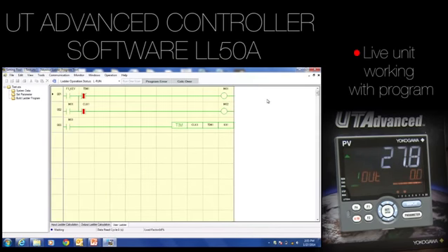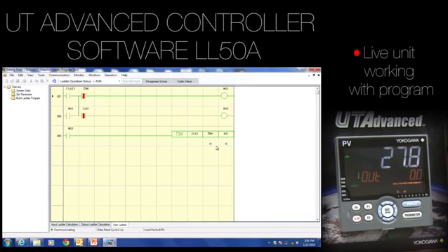Okay, so we got the ladder running here. The timer is off. The clock is pulsing. You don't see it so often, but it is. The other thing we don't see is the data in the timer. Any of the digital data, anything that's not a bit, can be displayed by turning on your display under Monitor, your detailed view. So if we click on the detailed view, we can see that the timer is set for 10 seconds because K01 is set for 10.